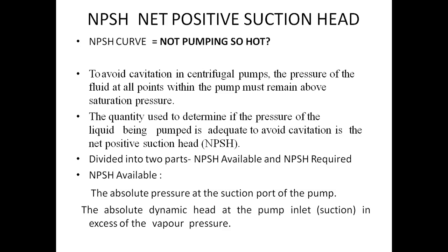It is divided into two parts, net positive suction head available and net positive suction head required. So net positive suction head available is the absolute pressure at the suction port of the pump, the absolute dynamic head at the pump inlet in excess of the vapor pressure.